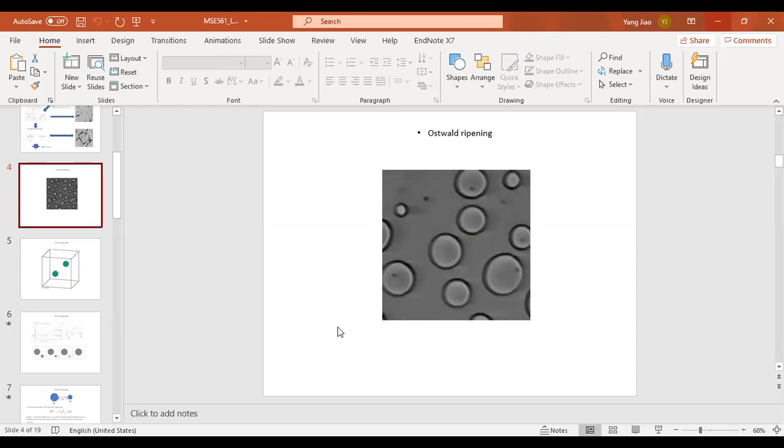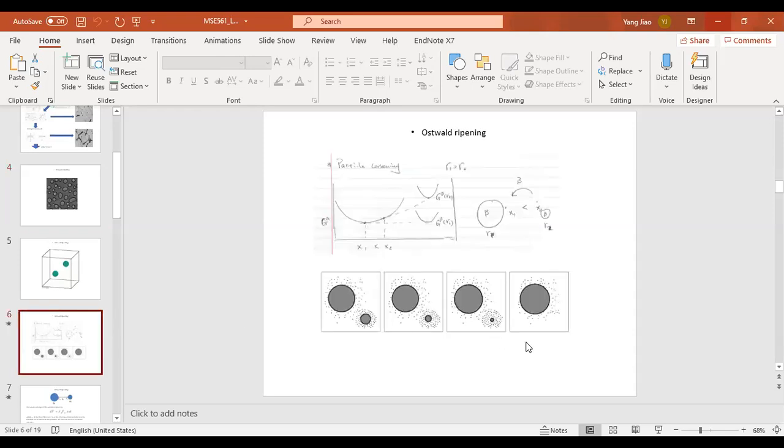Okay, so we call this the Ostwald ripening process, and I think the last lecture showed that this is again due to the Gibbs-Thomson effect. Because you have particles of different sizes or different curvature, their effective Gibbs free energies are different, and this leads to different equilibrium compositions of the solutes in the alpha phase region right near the particle surface.